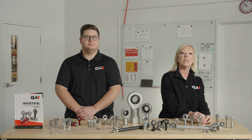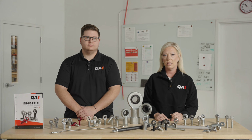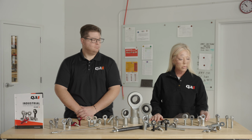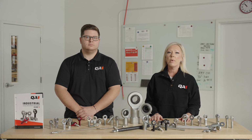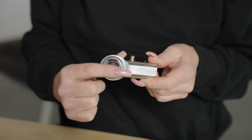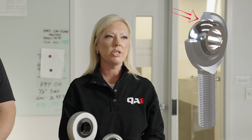They're commonly used in light-duty applications with moderate load and low oscillation needs. With two-piece rod ends, you can choose from metal-to-metal construction or select a self-lubricating liner. Metal-to-metal options like our C-Series are simple and durable. However, regular maintenance like lubricating is recommended. As we mentioned, QA1 does offer two-piece options that include a self-lubricating liner between the ball and the housing, that offers the benefit of maintenance-free performance and helps reduce noise and vibration.